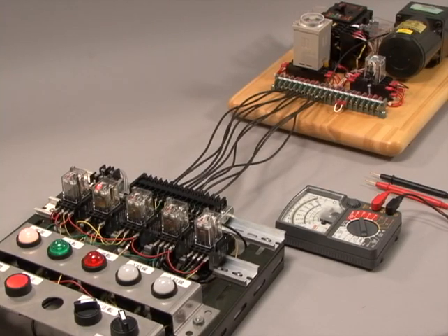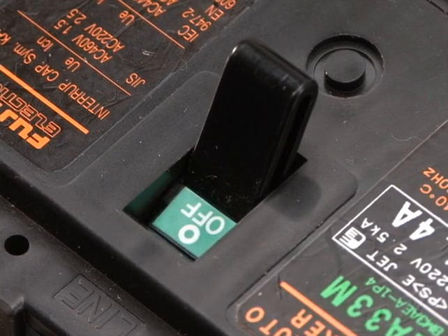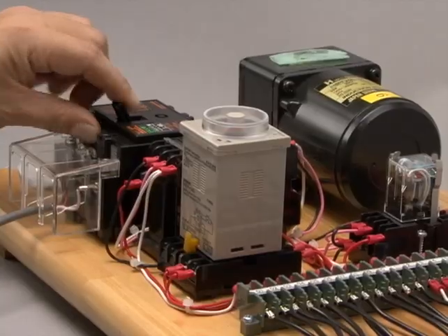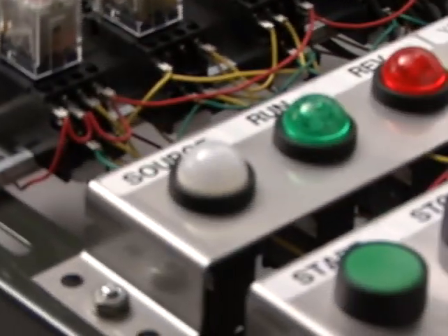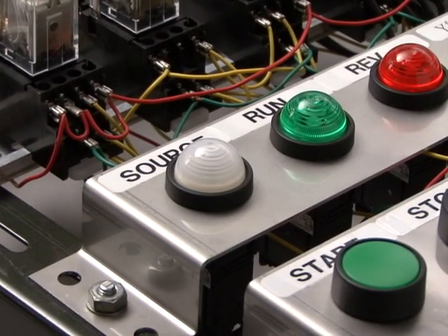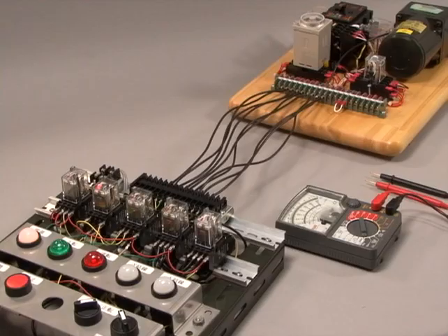Now let's think about how to locate defects with a tester using this circuit diagram. Here, let's assume a condition where the power source lamp does not illuminate, even when the MCCB is turned on. First, let's check the fuse.